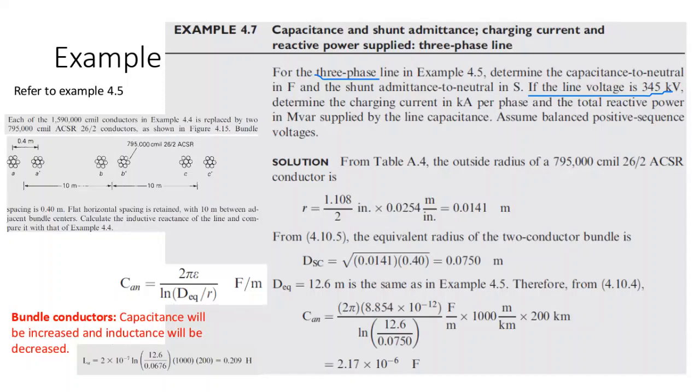It's written here, if the line voltage, and we're talking about three phase, they will not put in a parenthesis for you. It will say 11 kV will be three phase. But in the last exam, I put this in parentheses to make sure this is line to line voltage. When you read the textbook, you will not find this in parentheses. Line to line voltage, and you're talking about three phase. That's it. So it is line to line, not line to neutral.